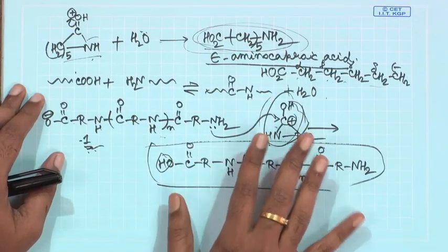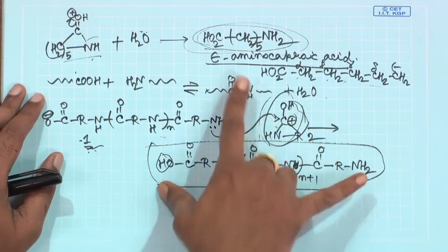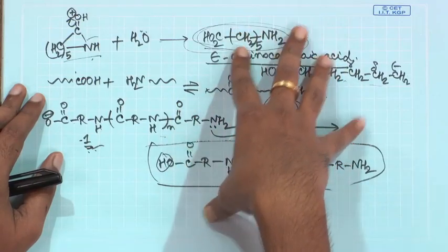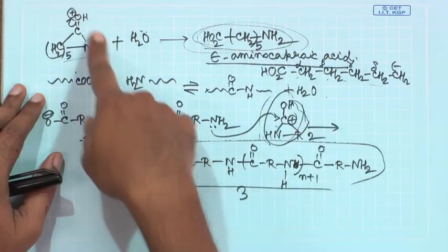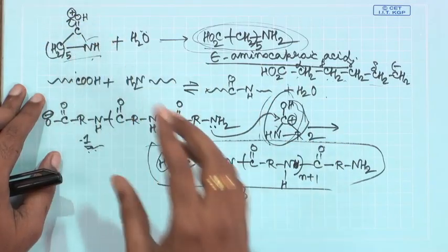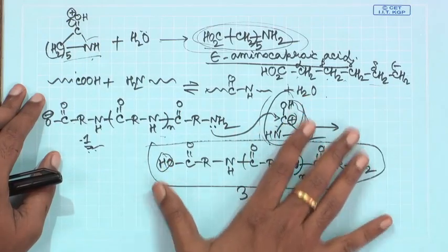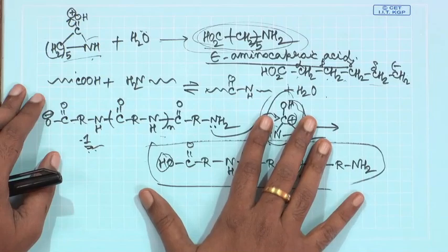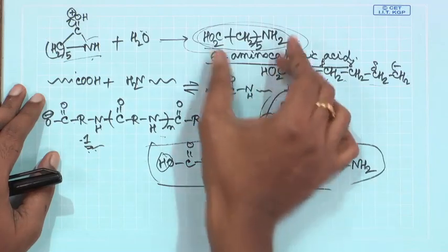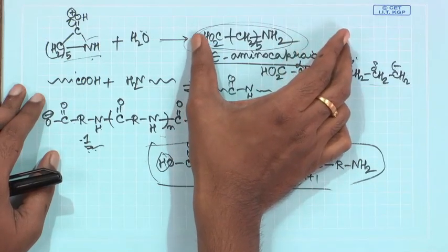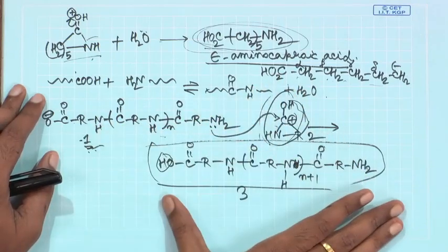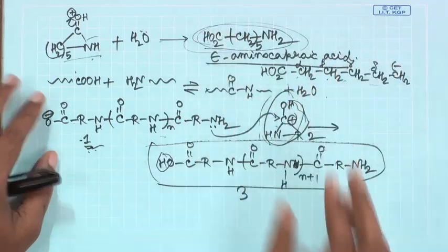Now, it turns out that this self amidation reaction only accounts for a few percent of the total polymerization in this caprolactam ring opening polymerization system. So, if you start with caprolactam, you are trying to get nylon 6 as the product, only a few percent of the reaction occurs through self amidation, mostly it passes through ring opening polymerization. So, basically it will only produce an oligomer and then it will directly go and it will activate this lactam and react further, instead of just increasing the chain all by itself.